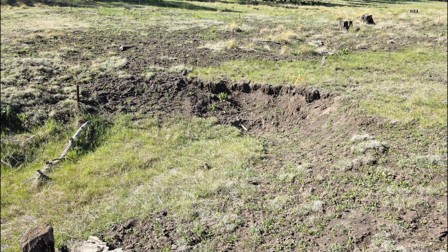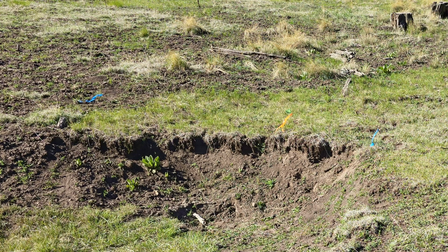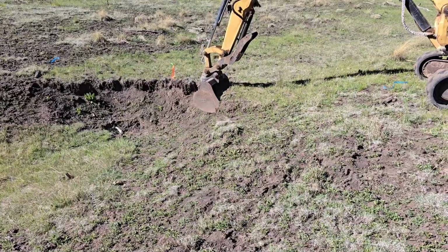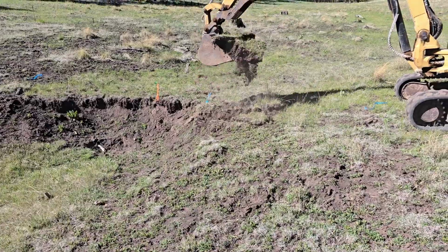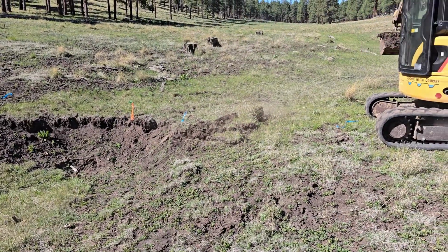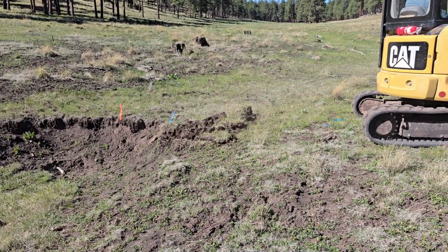Let's see how one of the head cuts was controlled on the Dye Ranch by using the vertical grade control technique. I used blue-colored plastic ribbon to show Don Smith, the excavator operator, where to dig for building the buried vertical grade control structure that was needed to control the head cut. Don began digging a trench that was perpendicular to the flow of water in the drainage. The lower edge of the trench followed the vertical face of the head cut.